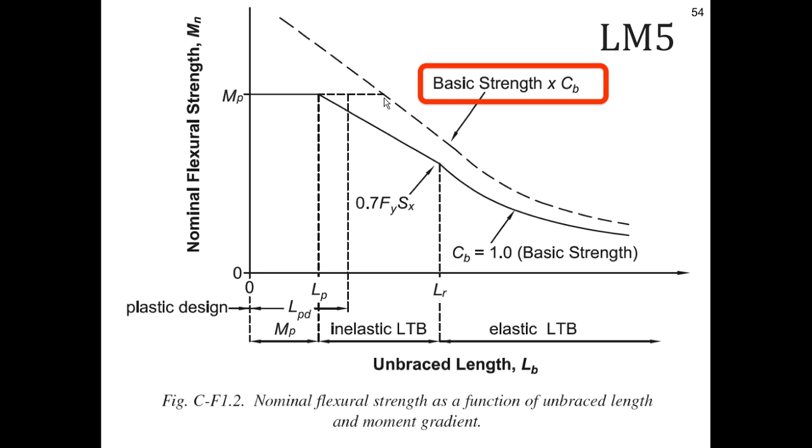Will Mastan handle steel box girder sections? Yes. Mastan is not going to capture local buckling, so web buckling or flange buckling in these box shapes. But if they were stocky enough, let's reduce the problem to a simpler one, and that's just HSS shapes. Then Mastan's going to be quite happy with that doubly symmetric shape, and you can pick off the database if it's an HSS shape. If it's a box shape, a unique shape, then you would need to calculate the plastic section modulus, the Z values about each axis, and input those into the program.